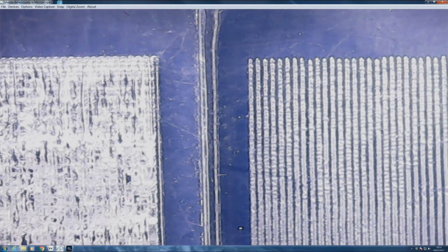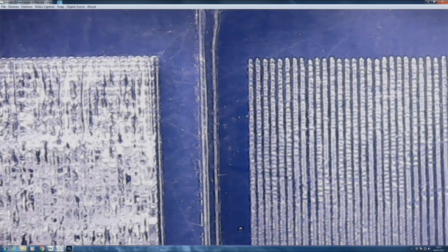Whereas on the right hand side, we have 400 millimeters a second, where the power is not getting a chance to settle at all, so we're probably getting dots on that side which are much closer to the spot size for the lens itself, which is around 0.075 to 0.1 of a millimeter.